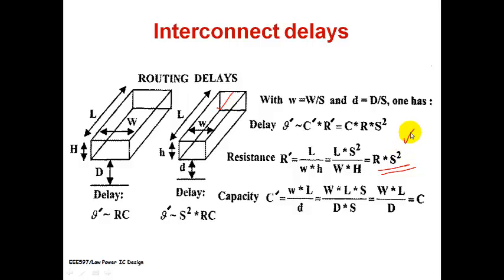It goes on increasing. To tell you particularly, previously for a 500 nanometer technology, we had 94 ohms of resistance for a 1 millimeter wire. In the same way, if I consider a 100 nanometer technology, the value is around 140 ohms. Compare this. So if I go for technology nodes less than 100 nanometer, it is still going to be worse.